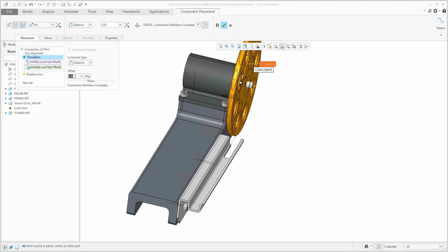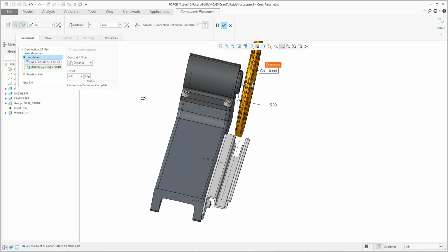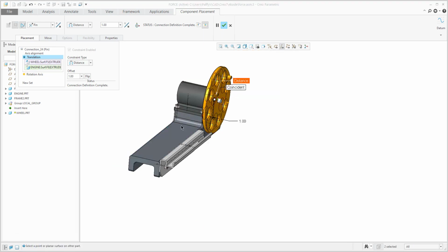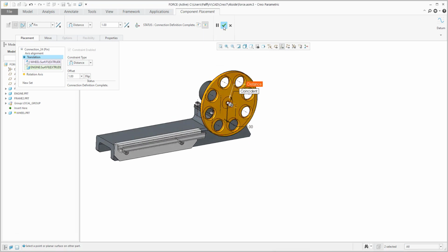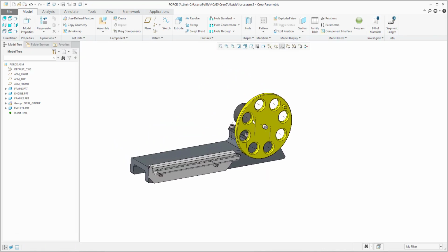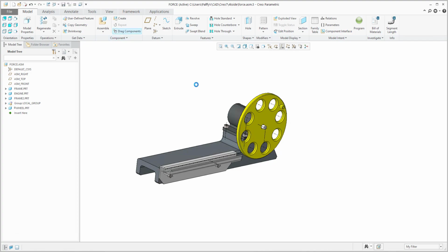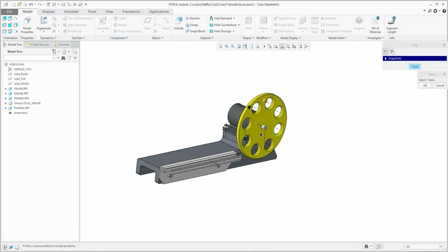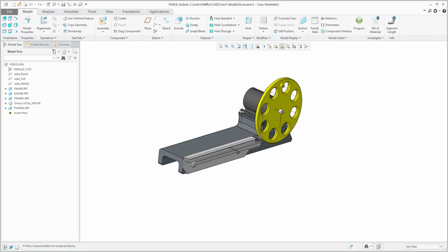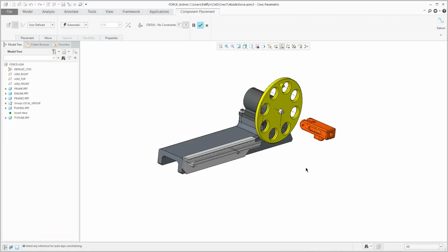So for example 5, or maybe 2, fine, great. So the first component is specified and I will confirm. What is good is that right now the first component is placed and you can check if the mechanism is working. So the pin connection is constrained correctly, and we can add the second component. It will be the stone.